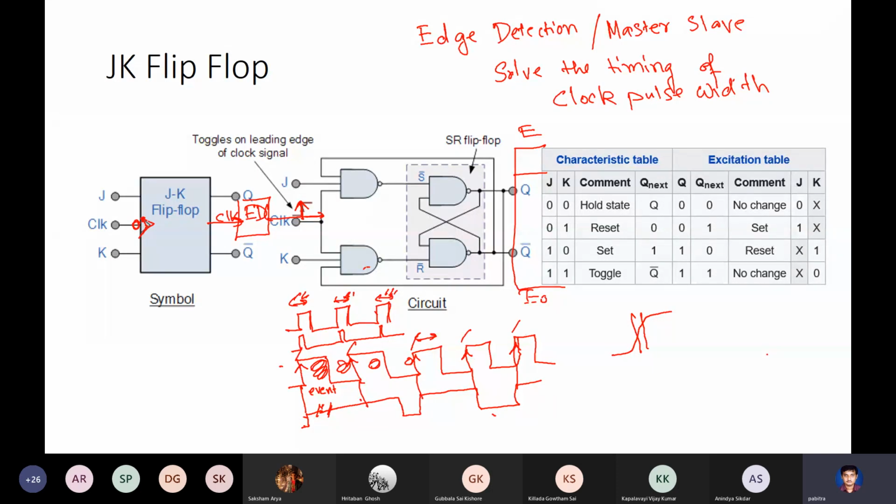So you have 2 inputs to these S and R blocks. One of the inputs is the external input. The other input is the current output. So in a sequential circuit, the current output is also considered as an input, because of this feedback. And then it's simple combinational analysis.